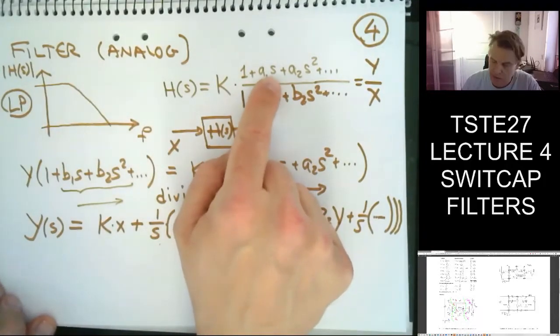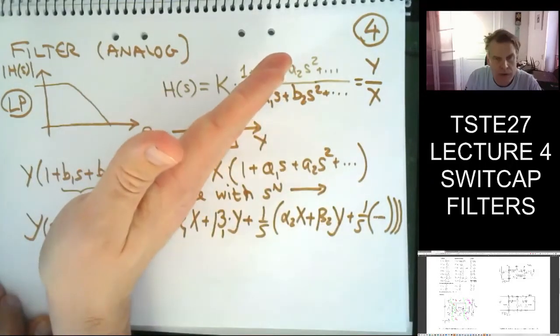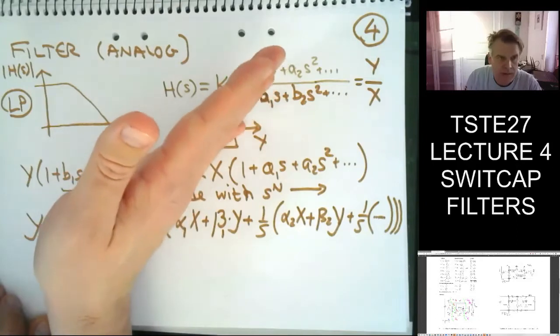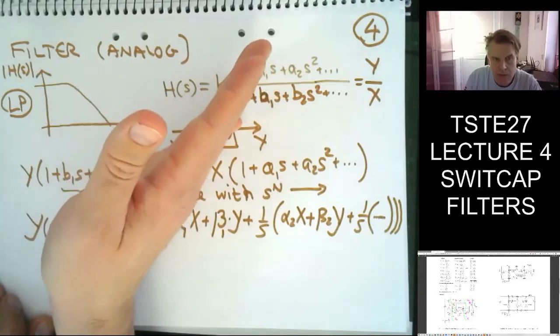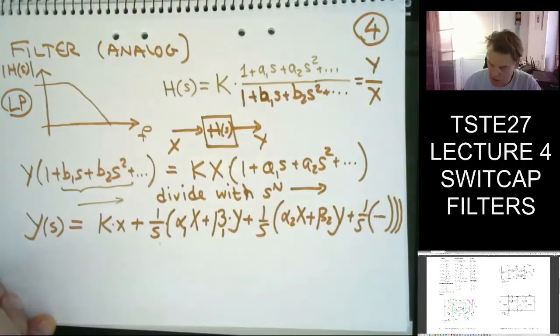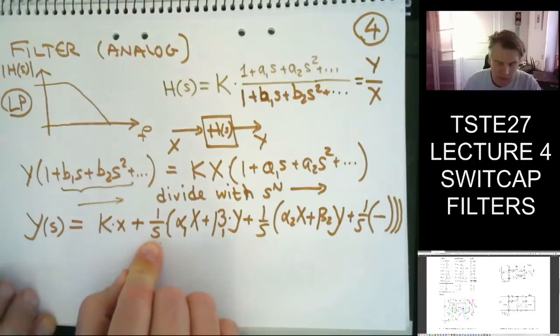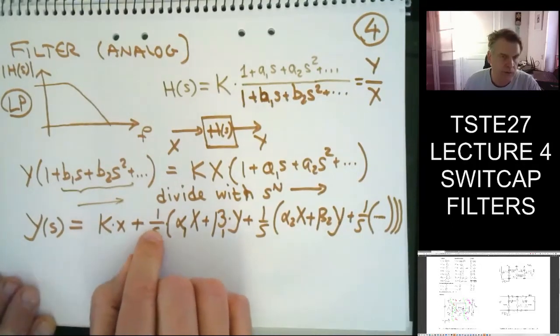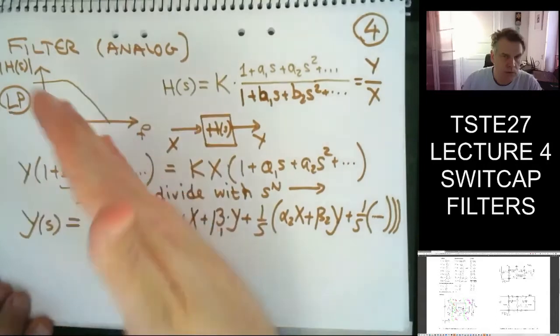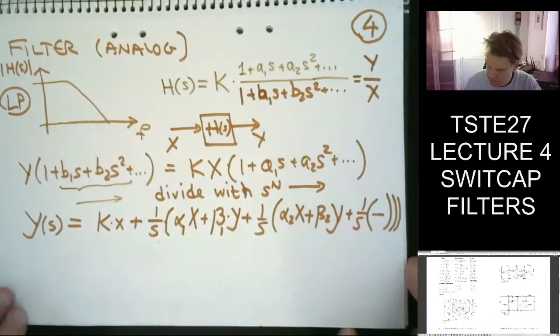In the frequency domain, the S curve points upwards for higher frequencies, so it has high gain for high frequencies, which means it will amplify noise. So typically the integrator 1 over S has nicer properties because for higher frequencies it's approximately 0. So I damp any additional noise or problems I might have.